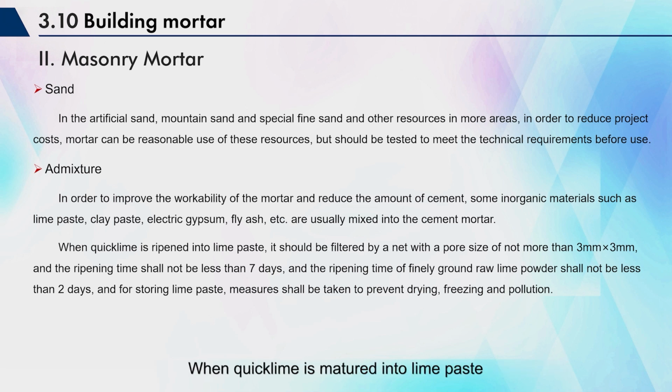When quicklime is matured into lime paste, a 3 mm × 3 mm mesh filter should be used for filtration, and the curing time should not be less than 7 days. The curing time of ground quicklime powder should not be less than 2 days. Measures should be taken to prevent drying, freezing, and pollution when storing lime paste.